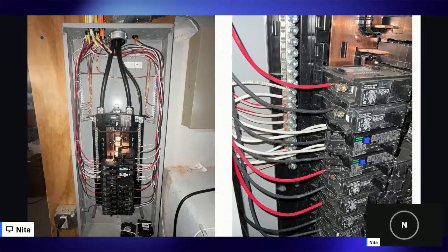Throughout my house, I have multiple rooms, multiple outlets, multiple lights, multiple appliances. Each one of my branch circuits is going to serve that. On a circuit, this is our circle now, when we talk about that circuit, we start at the source, we go to the load, come back to the neutral. I may have 2 outlets on one circuit. My neutral, the return wires, they come back and terminate here.